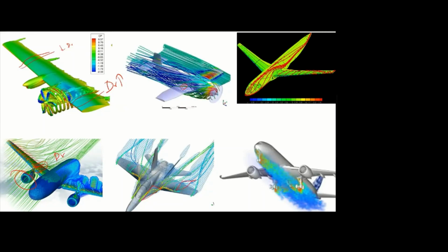And here you see the landing gear. So the landing gear also disturbs the flow over the complete aircraft. So all this interaction of flow increases the additional pressure drag. So here the fuselage. Because of this interaction of flow, we are getting additional pressure drag, that is called interference drag.